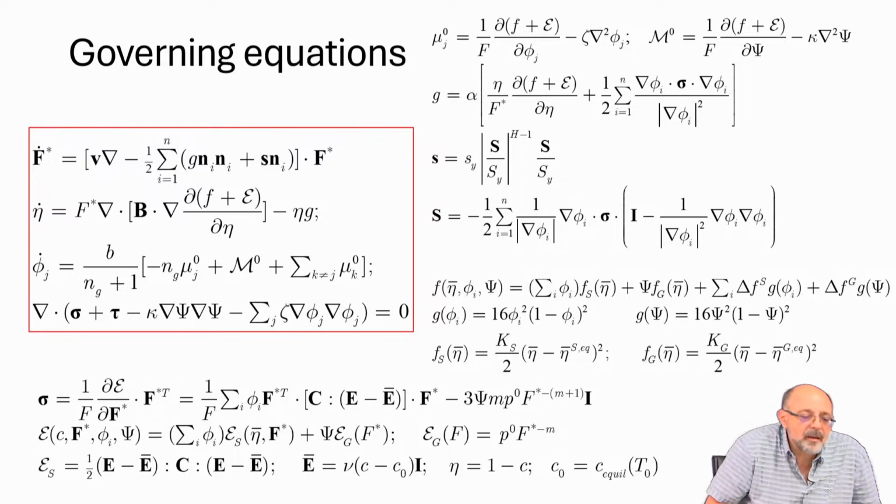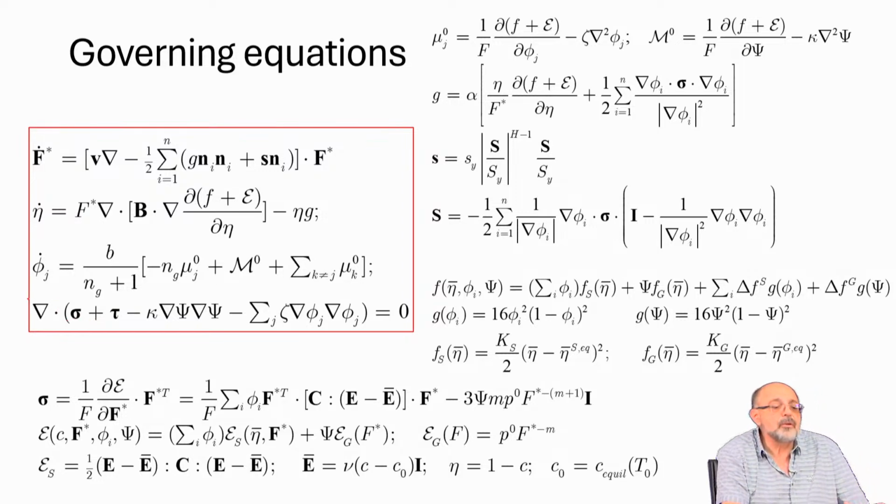So these are my equations. From Cauchy's equation of motion, the only part that remains is the divergence, but it's the divergence of the total stress. We drop out inertia because everything is very slow, a quasi-static process. We ignore, well, gravity. Other forces are much more important. So it's a quasi-equilibrium, divergence of total stress. And total stress is elastic, viscous, and capillary. Okay.